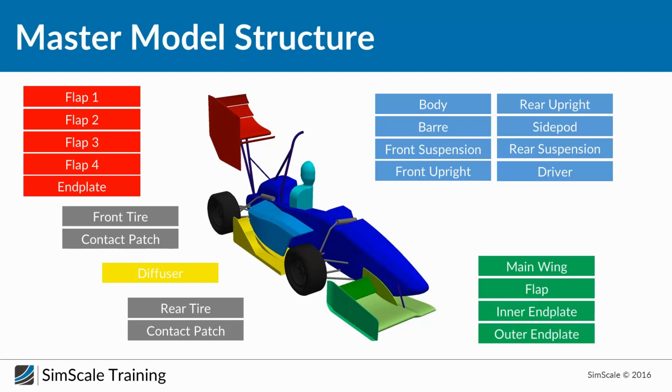And maybe just one last thing I will add, since we'll talk about this master model. The best thing is to create a model out of solid bodies, or at least which are watertight, then export every part as its own STL file, and then merge all STL files into one, which means we will just copy them all into one large file. The reason is, at SimScale right now you can only upload a single STL file, and a lot of CAD tools cannot handle STL files with multiple geometries inside, so therefore this is the best workaround. But we will write a step-by-step tutorial and provide it to you soon about model import together with the homework assignment.